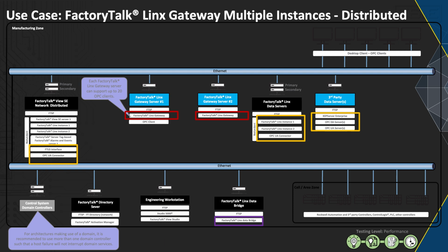Whatever you're using on the OPC UA side, as far as the OPC client side of this, it would have to be smart enough to know if one of these goes down and switch over to the other one. We don't handle the switching mechanism in here. That's true across the board with any OPC UA vendor that I'm aware of. The switching mechanism is handled by the client, not the server itself. That's true with Kepware and some other vendors that we deal with.